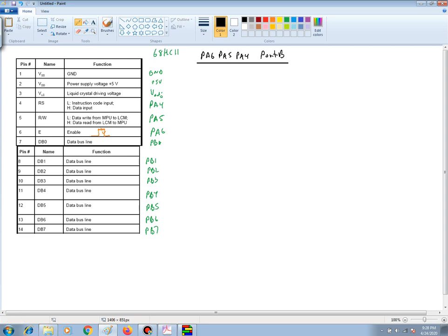One of the very first things, of course, is to start off with an origin line. So we have an origin, and let's say that's going to be at F800. And we'd probably have to take care of the stack, since we're probably going to be running this under single chip mode. So let's load the stack with a value of, say, 00F0. That'll leave us a lot of space so that we can use our stack.